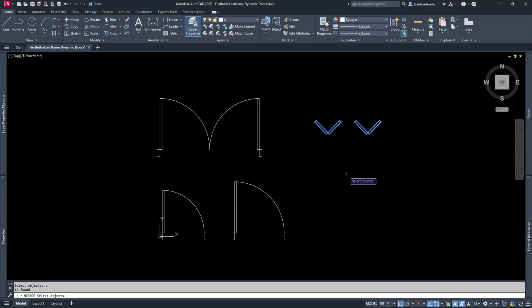Okay, and then I'm going to tap the escape key. And one more, if you don't mind. I'm going to draw a line from here to there and enter. Let's say I want to move this line. Well, that was the last object I drew, so all I have to do is type L and enter, and it picks the last object.